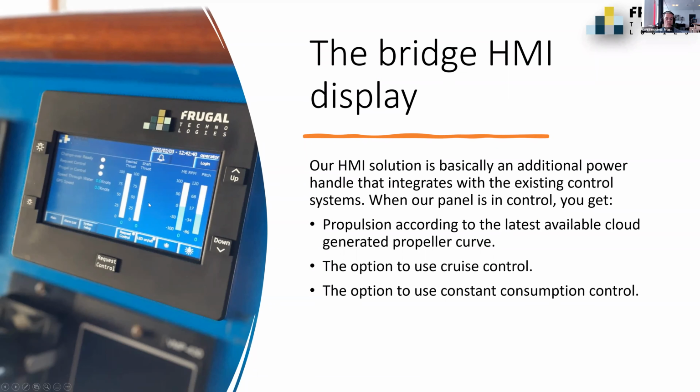It doesn't replace any of the existing control mechanisms. It doesn't replace any of the safety mechanisms, but it does add some safety mechanisms when our system is in control. And the thing you get, of course, is that you always get to run your vessel at the latest available propeller curve, because we collect data continuously about the vessel, and that data is also continuously validated against the previous set of data we have to make better propeller curves, if possible. And then those are deployed to the vessel. So it keeps optimizing all the time, feeds off the data we collect, feeds off what we know from the propeller curves we've already had deployed, and it feeds off the performance measurements that we can do all the time.